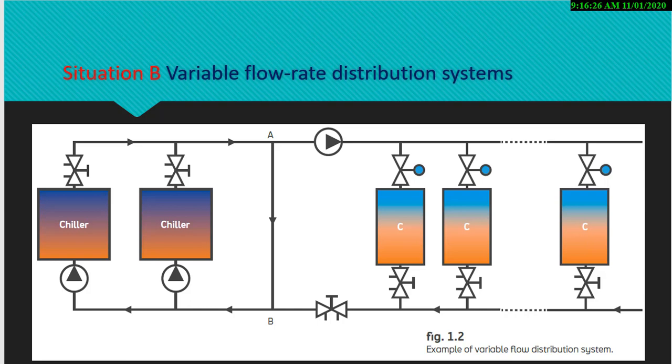However, as soon as the proportional valves begin to close, the differential pressure can increase considerably, generating noise and regulating disturbance before the pump can react. Trying to avoid overflows this way will simply make the problem of an inadequate flow rate worse.